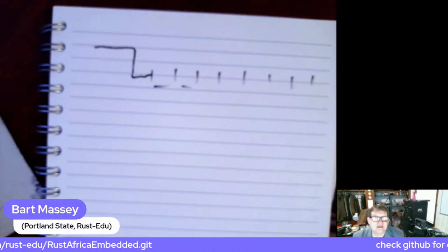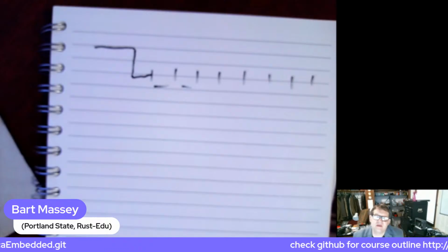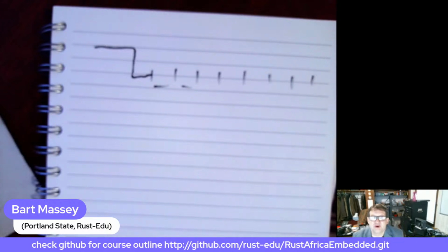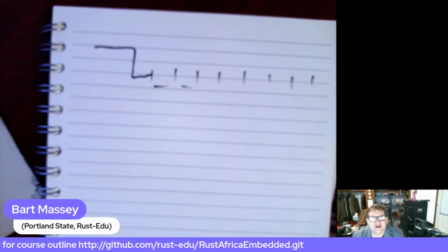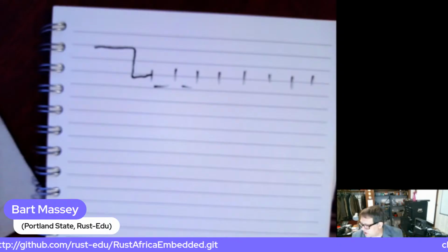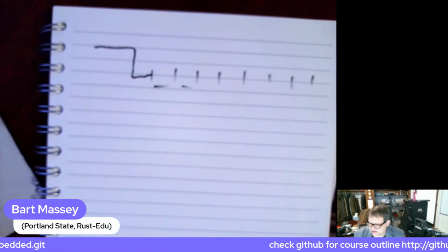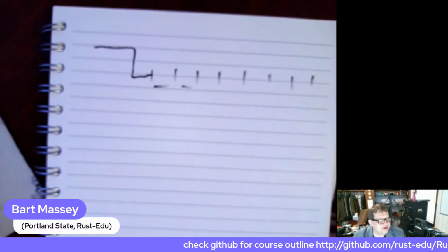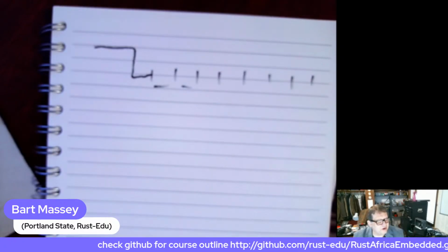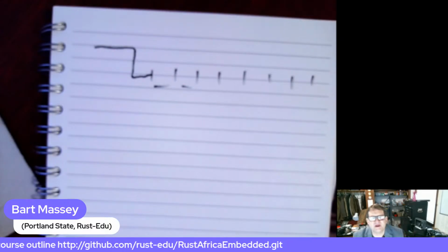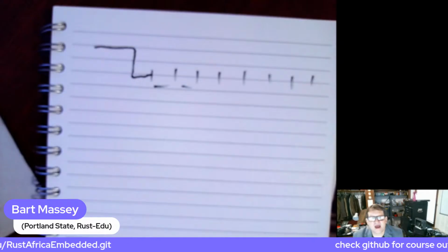So it's a very fast serial port. In olden times, a serial port that could send at 20,000 bits per second was considered pretty fast, but modern stuff is nuts. And so if you were to look with an oscilloscope at the output of this UART as it's transmitting, it'd be this pin right here, 1.08, port 1, pin 8. If you look at the output of this UART as it's transmitting, you'll just see a series of highs and lows corresponding to bits of the byte.